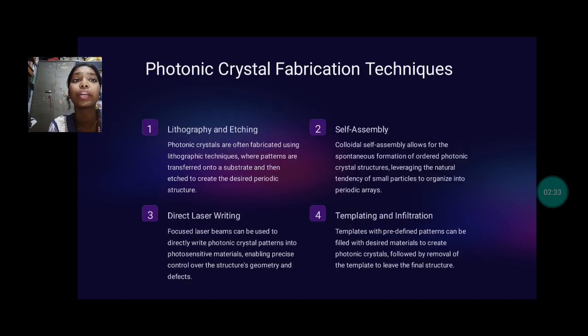Now, photonic crystal fabrication techniques. Lithography and etching, self-assembly, direct laser writing, templating and infiltration. Now, step 1. Lithography and etching. Photonic crystals are often fabricated using lithographic techniques where patterns are transferred onto a substrate and then etched to create the desired periodic structure.